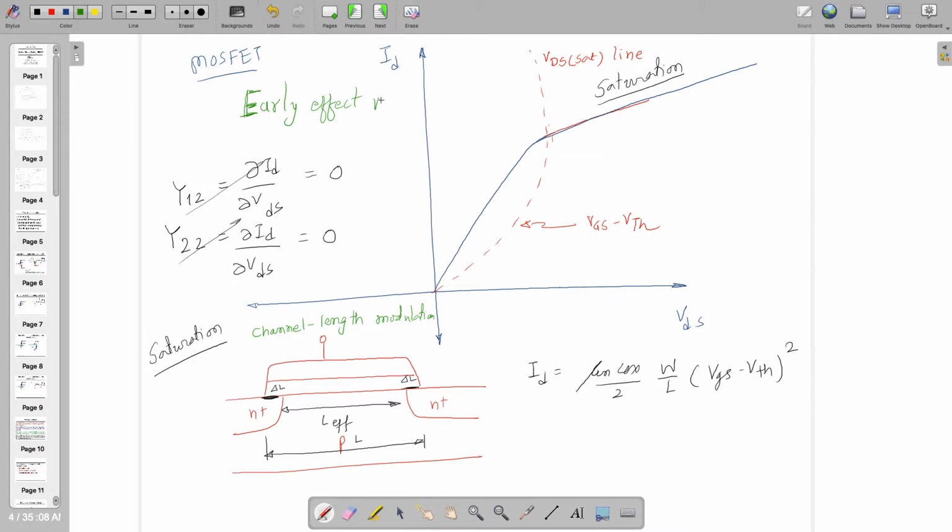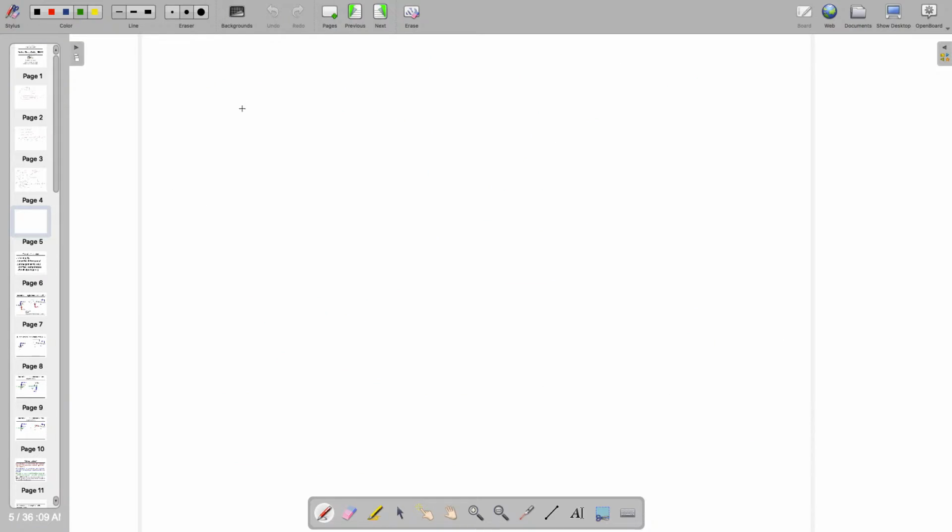This is the case for BJT. And for MOSFET, it's known as channel length modulation, because channel length is actually decreased by some factor, or in some cases it increases also, and the equation is changed by 1 plus lambda VDS, where VDS is the drain to source voltage and lambda is delta L by L. So that's the ratio of channel length, right? So the equation has changed.